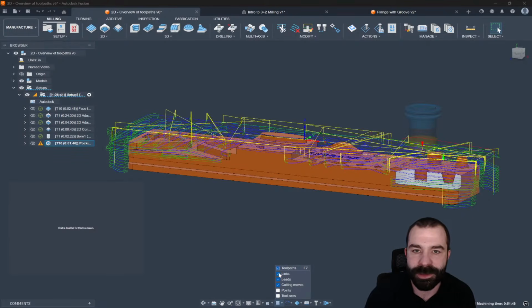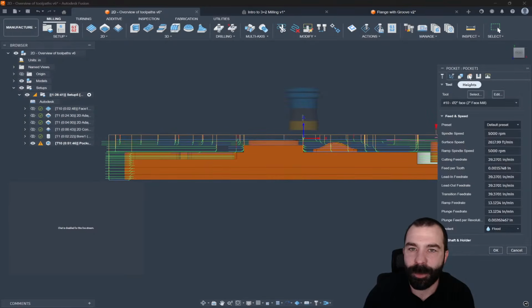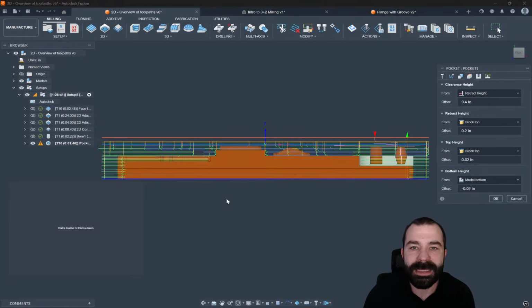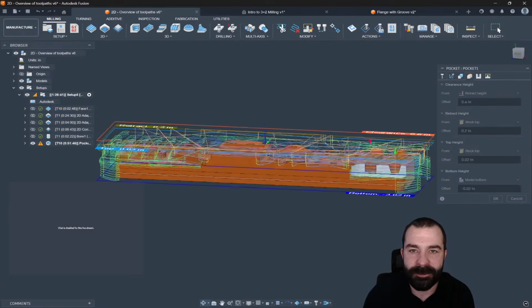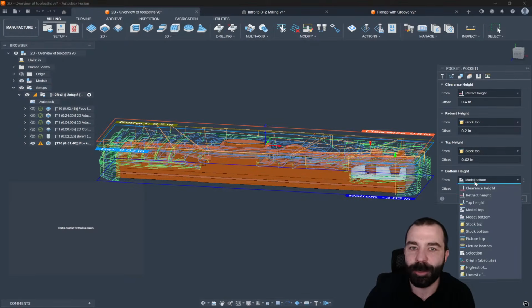So let me get the points turned off. I turned the wrong thing off, but it all still works the same, right? So again, you have your clearance heights, things of that nature. I can jump over to the heights tab. This is a roughing toolpath, so we don't have a feed height anywhere hidden in here, but you could manipulate further than here. So if I wanted to limit this toolpath by not going lower than a specific pocket, same rule kind of applies.